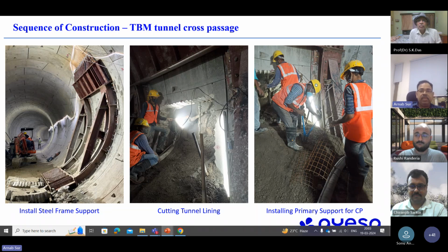But yes, we can go for fiber reinforced concrete. The problem is that there are limitations. With very good soil or rock conditions, where the forces in the tunnel lining are primarily axial and bending is very little, fiber reinforced concrete can be used successfully. Okay. For soft ground conditions, it is difficult.